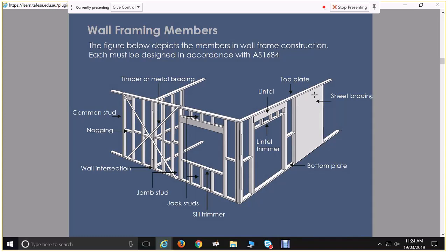So if you're using sheet bracing, one of the drawbacks of it is for your unbraced section, you have to pack those studs out. So with the circular saw, you just cut off lots of strips and you nail that to each of your studs. Or you just brace the whole thing. Carry that sheet bracing all the way through. So I like that approach personally.